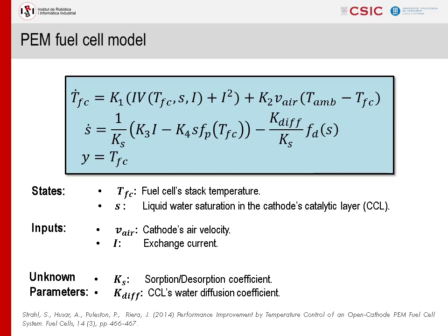Furthermore, it is assumed that the temperature can be measured, but the liquid-water saturation cannot. Additionally, there exist multiple techniques to measure the parameters K1, K2, K3 and K4. However, there is no reliable method to measure the parameters Ks and Kdiff. The objective of the adaptive observer will be to generate an estimation of the liquid-water saturation S, and the unknown parameters related to the water dynamics, Ks and Kdiff.